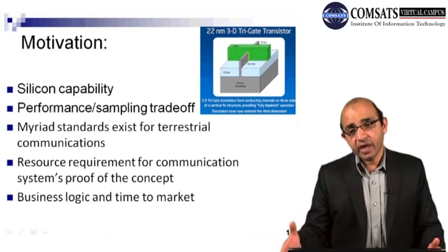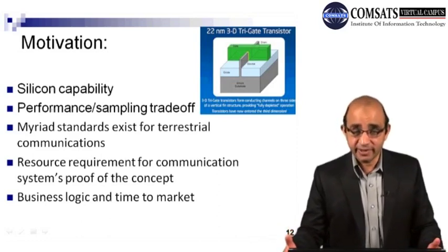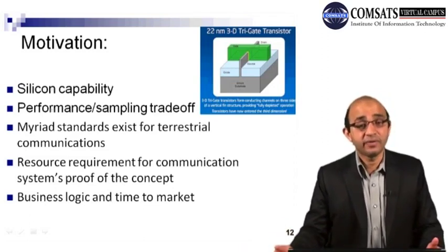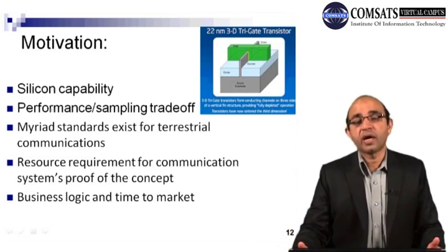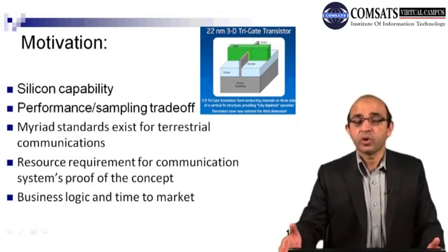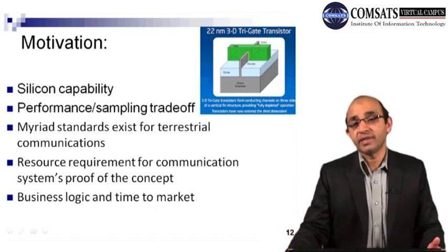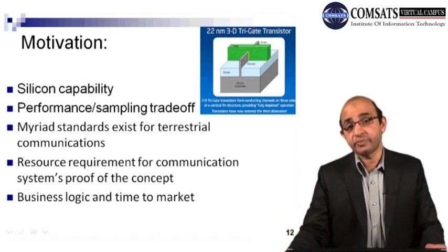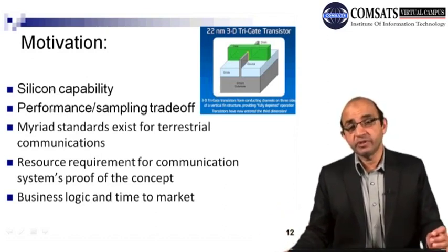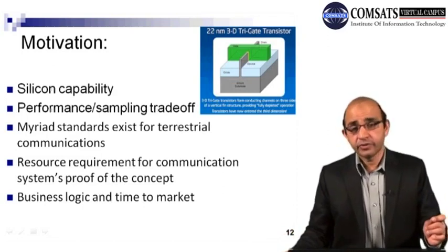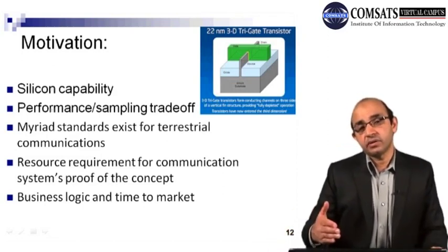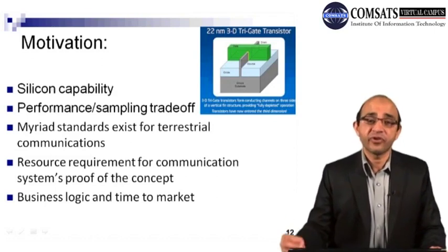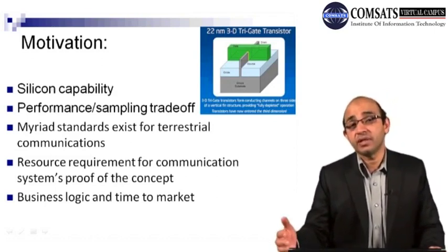But if I want to design a flexible system, where I want to get rid of this hardware-based system, or I want to avoid encoding all the filters, all the modulators, all the algorithms within the hardware by using specific ASICs, then I can have a system, or I can design, a software that can perform all the required functionality.